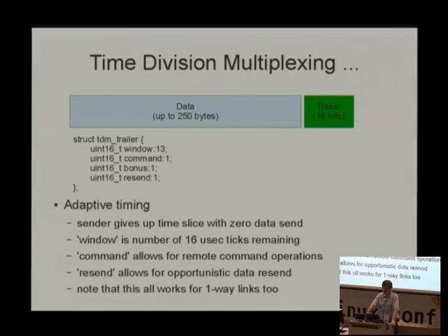And the resend bit is for increased reliability of commands going to the plane. It's supposed to be a transparent serial stream, right? The idea is that you have a radio at either end, you inject bytes in a TTL serial port at one end, they come out the same at the other. But you can lose packets. It's difficult to do a transparent serial stream when you can lose packets. And acknowledgement packets are a great pain because any acknowledgement scheme requires that you have two-way communication. And we wanted all of the features of this radio to work when you only have one-way communication, right?